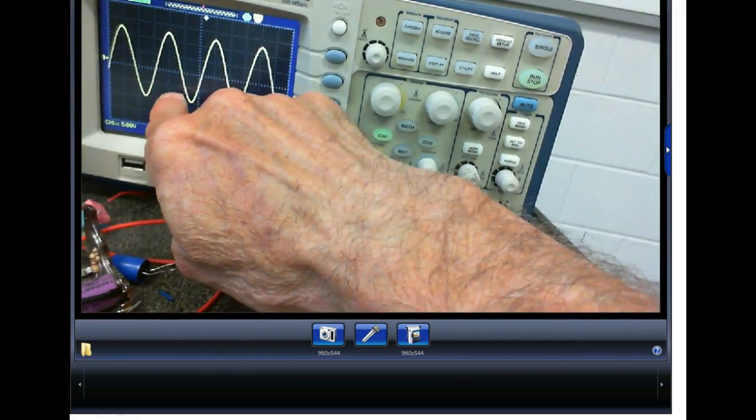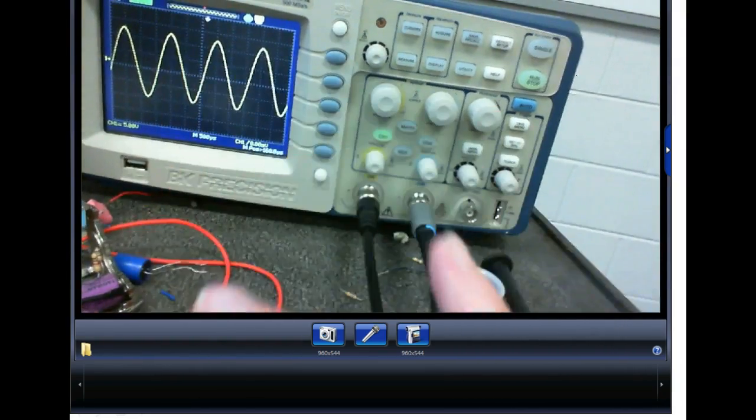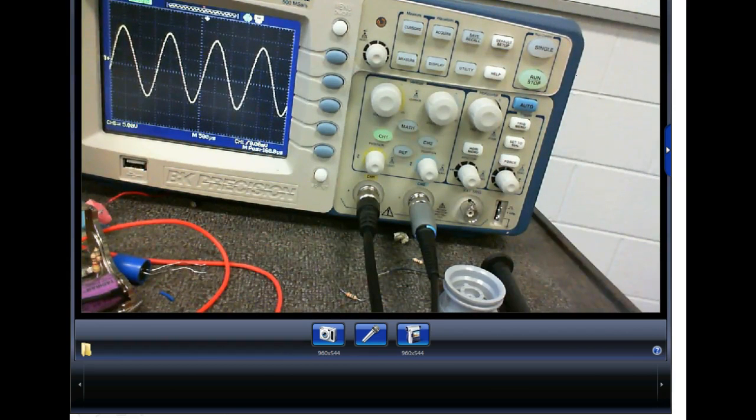So I got it on 5 volts per division. That'd be 5, 10, 15, 20, 21, 22, 23 volts peak to peak. So what would that measure on a meter? First of all, what would I do? I divide this by 2 and get what? Then peak, and then multiply it by 0.707. 8.1. And so that'd be 8.1 volts RMS, right? Are we okay? You okay? 23.